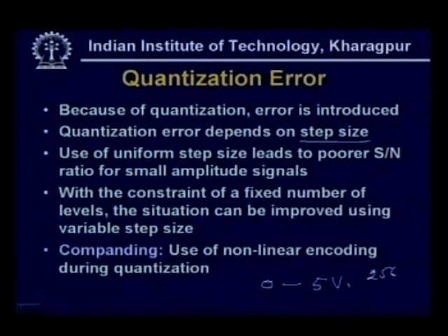So, the step size is essentially 5 volt by 256. Any intermediate levels between these will be translated into those discrete values, and that will lead to error.